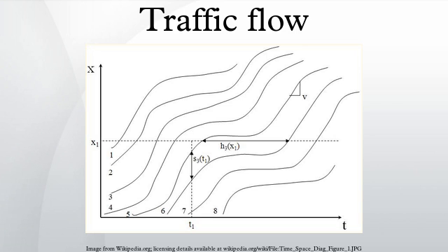Breakdown condition occurs when traffic becomes unstable and exceeds 67 vehicles per mile. Jam density refers to extreme traffic density associated with completely stopped traffic flow, usually in the range of 185–250 vehicles per mile per lane. However, calculations within congested networks are more complex and rely more on empirical studies and extrapolations from actual road counts. Because these are often urban or suburban in nature, other factors also dictate the optimum conditions.